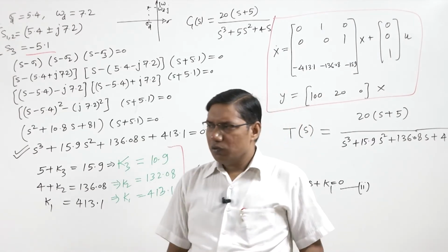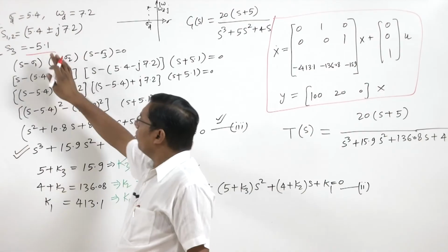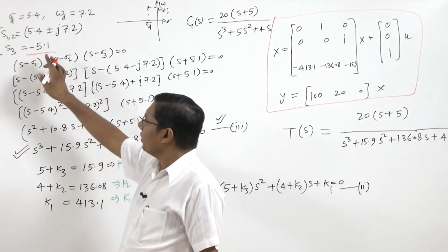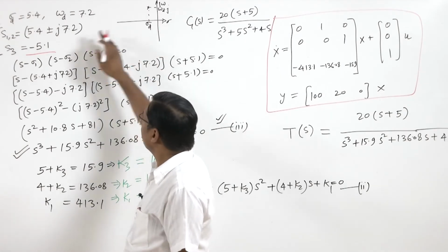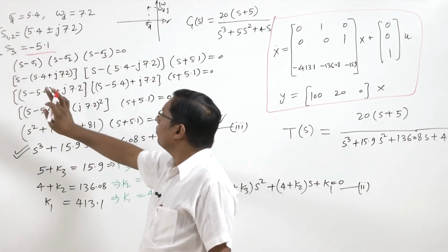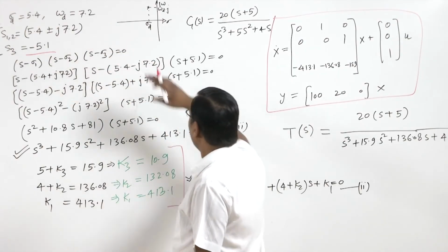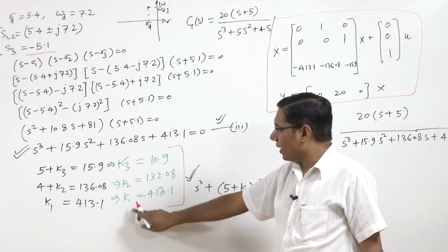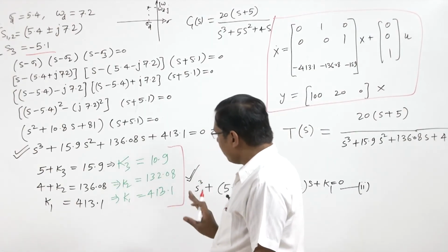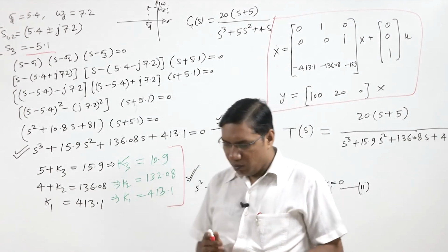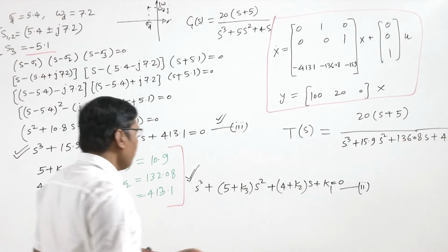We can also select this value maybe very higher, so we can put this pole very far from the real part of the dominant pole, maybe at S3 equal to 30 or 50, and we can find the value of gains corresponding to this value. So we can put all these system poles at the desired locations.